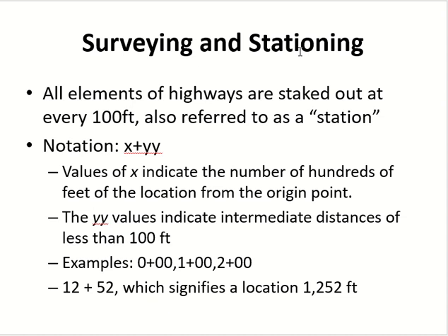In the geometric design, the most important element is surveying and stationing. Okay, we have already taken this course. So, station is what? A station is what? 100 feet. 100 feet is a station. 100 feet from where? Origin of the road. From the origin of the road or any point. From your reference point. Okay. So, from the reference point, every 100 feet is considered as one station. Okay. From the reference point.